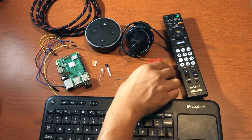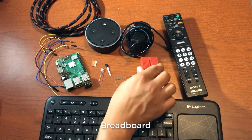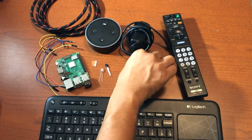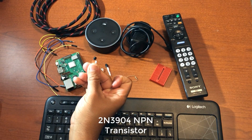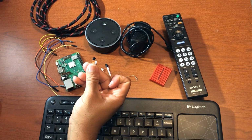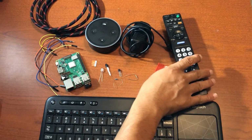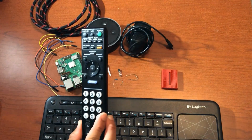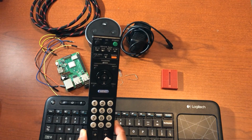Next, we'll need a small breadboard, and we'll use this to connect our circuit. We also have a transistor, an NPN transistor that we'll use to boost the signal to the infrared LED. Then a TV, of course, that we want to control, and the corresponding IR remote for the TV.